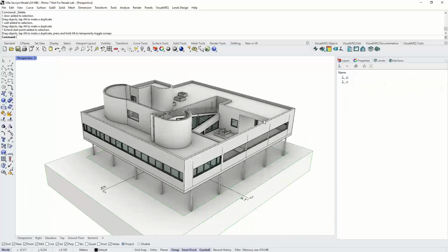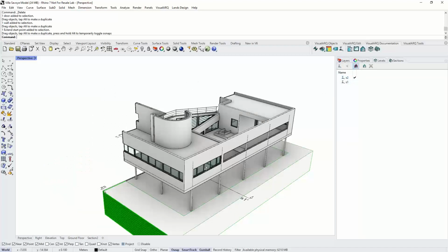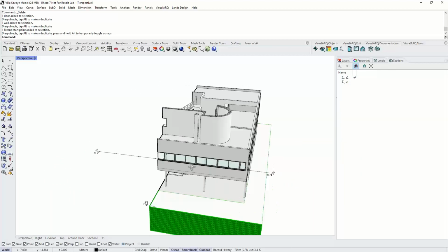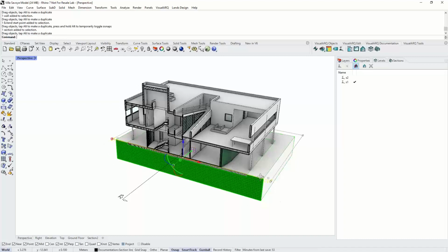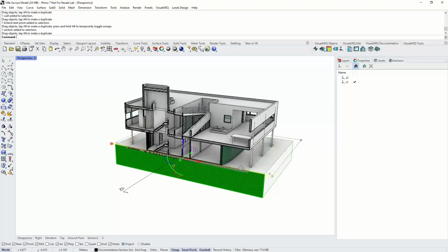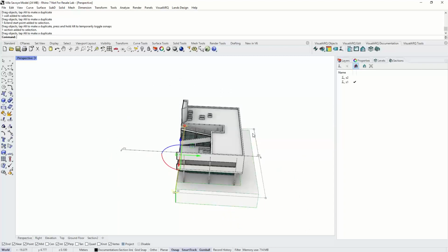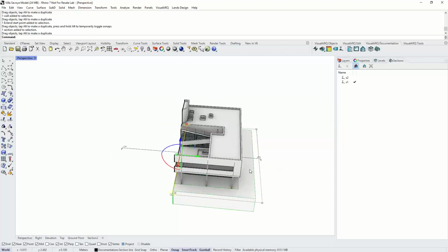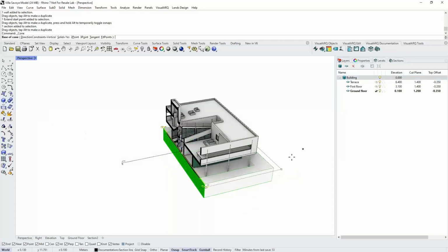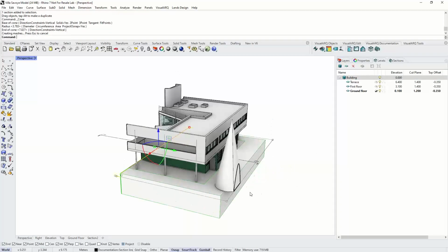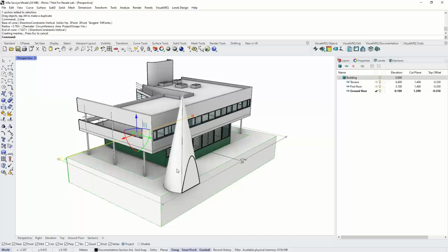So in a similar way, we've got the section manager. So here we can create new section lines, and from here we can just switch from one section to another. Okay. And of course, they are related to the position of this section line. Just take into account that these section lines have an area, so they will only show what is inside the boundaries of this area. So whatever we draw in here. Okay, for example, if we draw this kind of cone, so only what is inside its limits will show up in that view.